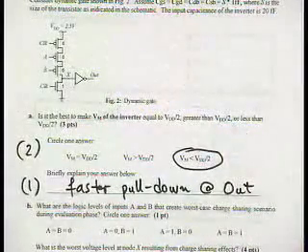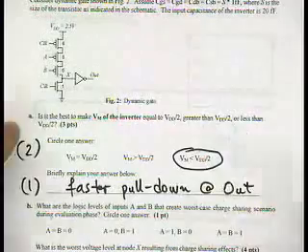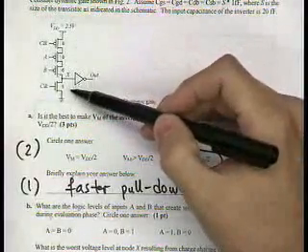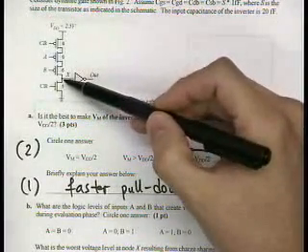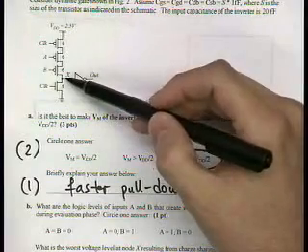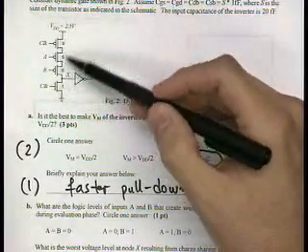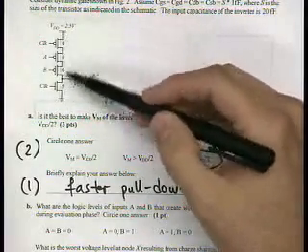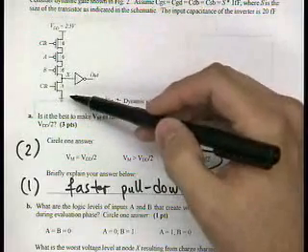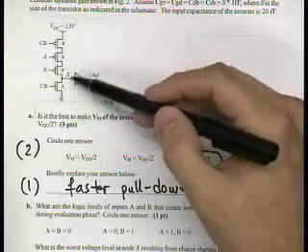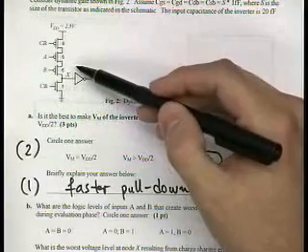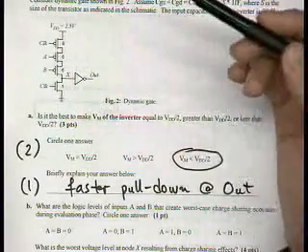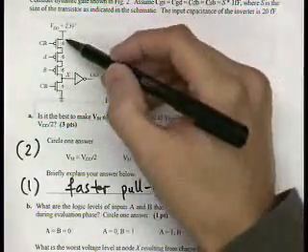So for the charge sharing, what you want is basically, in the pre-discharge phase, you discharge your capacitance to 0, and then what you want to do is see how much charge contamination you can inject into that node to bring that voltage up from 0 by some delta V. So that is in the evaluation phase.